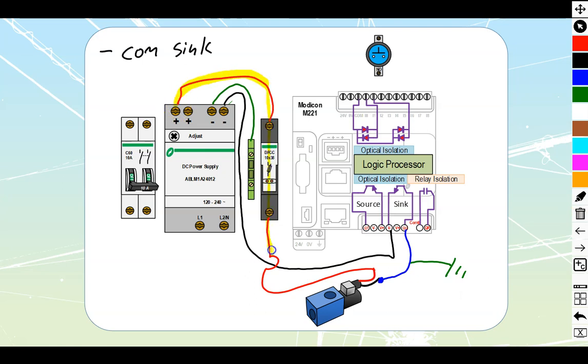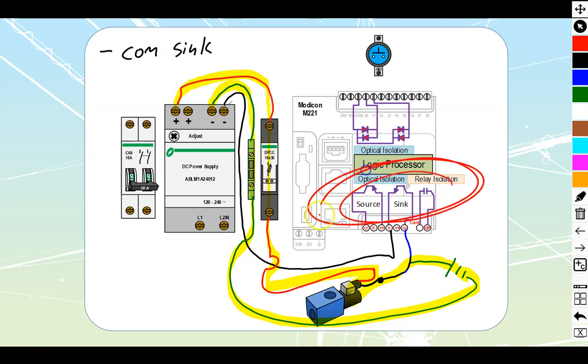Follow this through. We've got a positive tracking through all the way into here, going through our solenoid, and then we hit this. As soon as we hit that ground fault, we are then going to be able to track back through the ground path itself. So back through the boxes, the enclosures, and things like that. We could track back through all the rest of my bonding system to my supply over here. And what you see is that we have unwanted operation of this solenoid, even though the PLC itself over here is not calling for it. This is going to be a danger for us.